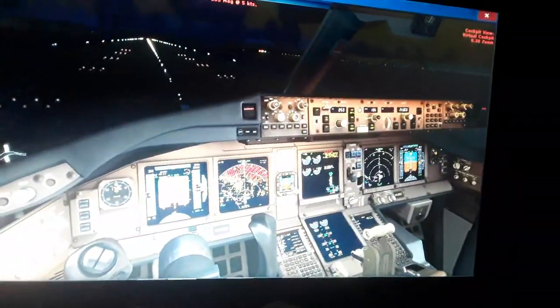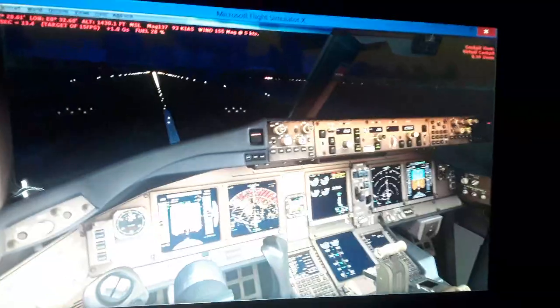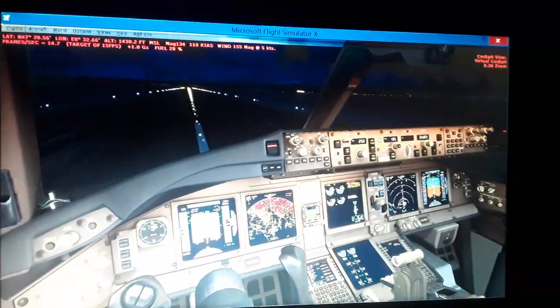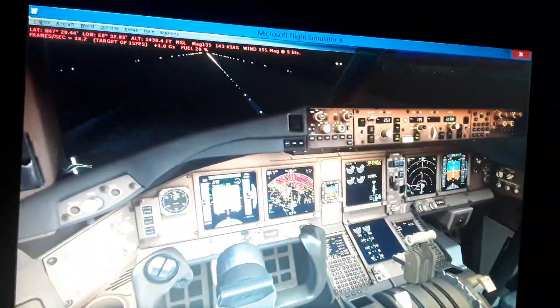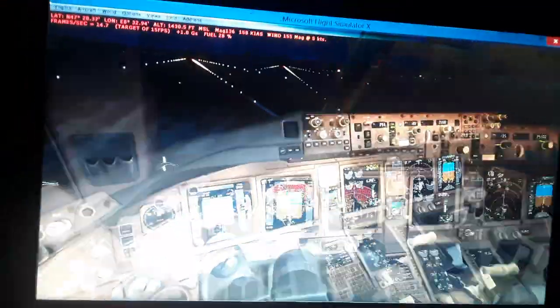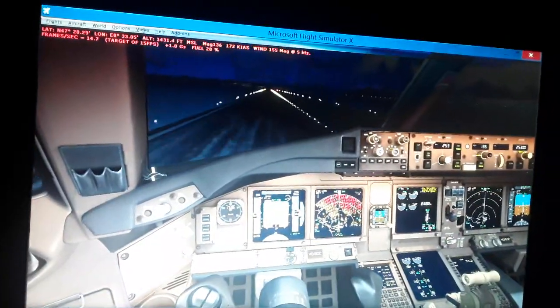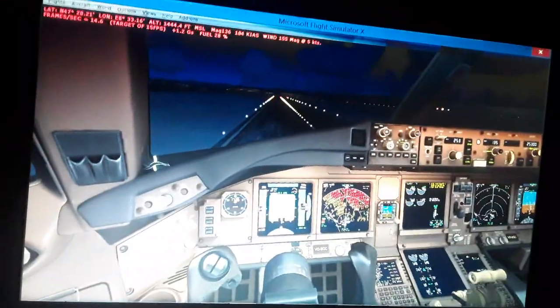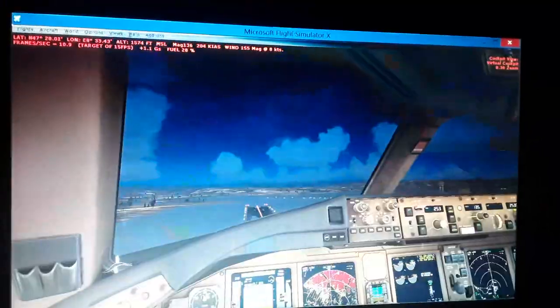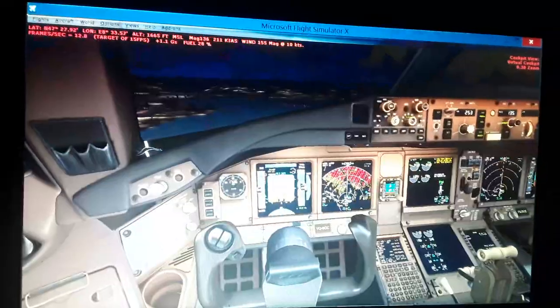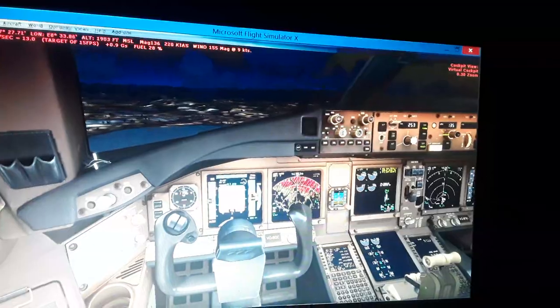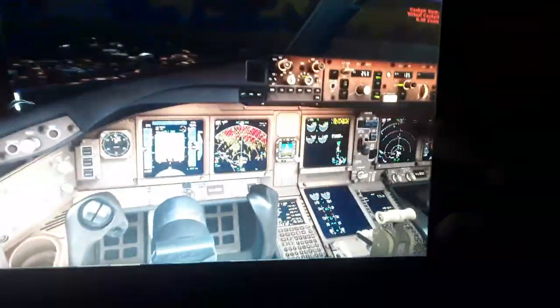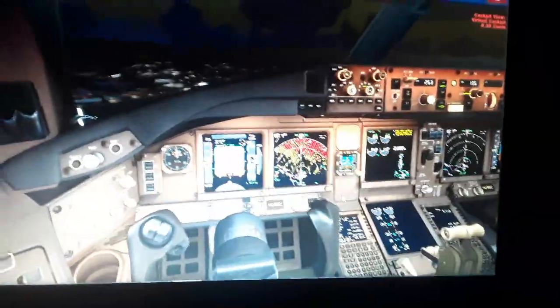So we need only 15 degrees, the flap setting for the takeoff. So we have 130 knots, V1, we rotate, and V2, and we take off. So we need also to pitch down a little bit, not climb so swiftly. Landing gear up, we have positive rate of climb.